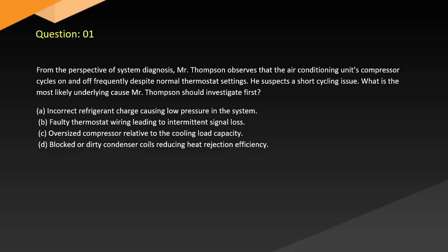A. Incorrect refrigerant charge causing low pressure in the system. B. Faulty thermostat wiring leading to intermittent signal loss. C. Oversized compressor relative to the cooling load capacity. D. Blocked or dirty condenser coils reducing heat rejection efficiency.